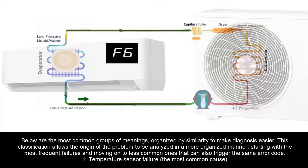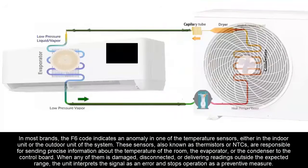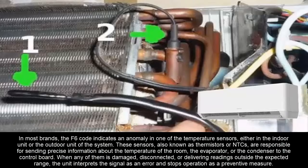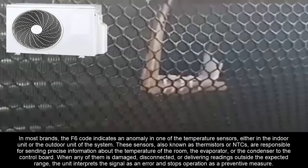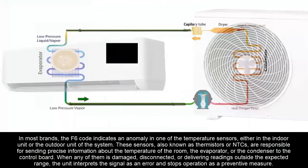1. Temperature sensor failure, the most common cause. In most brands, the F6 code indicates an anomaly in one of the temperature sensors, either in the indoor unit or the outdoor unit of the system. These sensors, also known as thermistors or NTCs, are responsible for sending precise information about the temperature of the room, the evaporator, or the condenser to the control board. When any of them is damaged, shorted, disconnected, or out of range, the unit interprets the signal as an error and stops operation as a preventive measure.